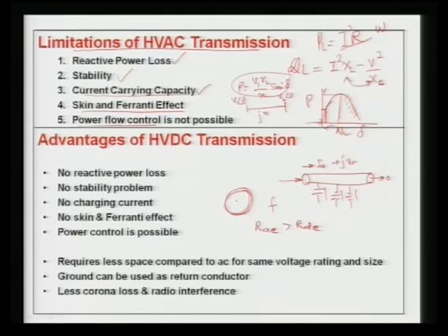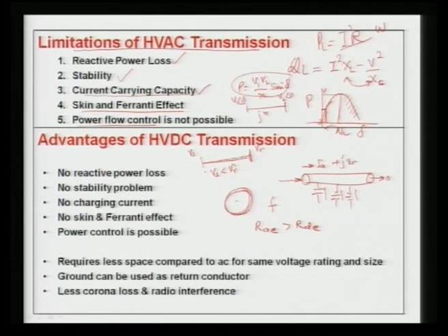The Ferranti effect, which is basically, if these two systems here, the big transmission line is there, and this is called V sending end voltage and this is your receiving end voltage. At lightly loaded or no load condition, the Vs magnitude, I am talking about, is less than, sometimes, your Vr, and this is called the Ferranti effect. This is due to the charging, basically the capacitive charging due to this conductor with respect to ground.